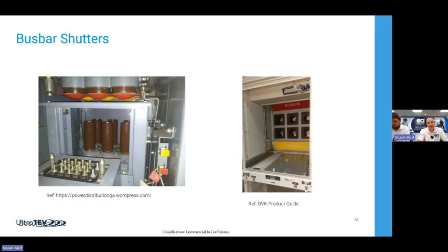If you've got high humidity, I think one of them was associated with the heaters not being on in the panel as well. So if you've got a bit of humidity and a relatively short distance between the two, you can quite easily get a flashover between there, and you start getting partial discharge activity. So if you've got some panels in your switch room and the breakers racked down, but these are there, definitely always have a listen round with your ultrasonic microphone as a minimum, and take some TEV readings off the breaker still, even though it's not physically connected, just to make sure there's nothing major going on there.